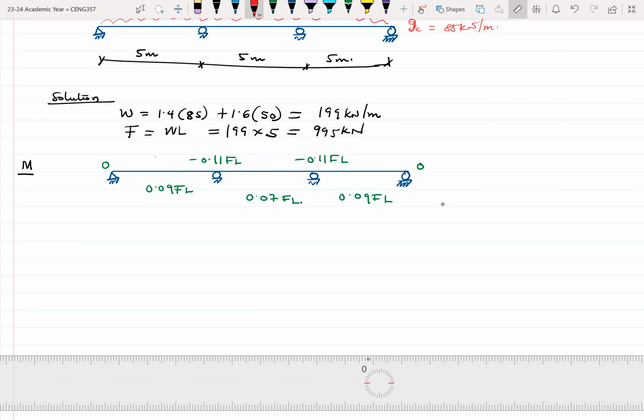Okay. So it means that you have to design the beam for, let me call this one span 1, span 2, span 3. So you have to design the beam for bending in span 1, bending in span 2, bending in span 3. They're also designed for moment over the support. So 5 calculations will be done. Okay, but because some of them are similar, you can group them together and then you end up with 3 different calculations.